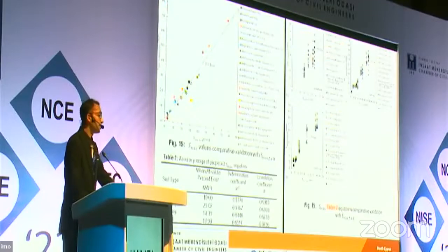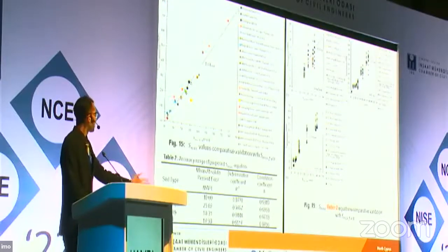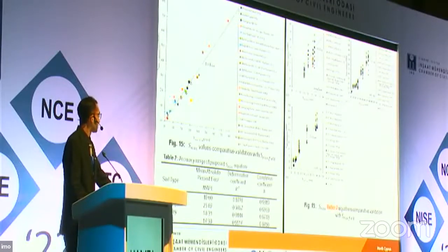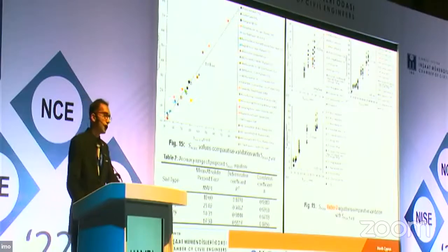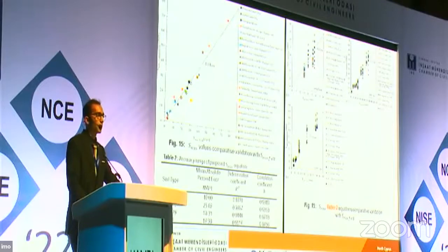So we have validated our modified equation with the field data, and overall the performance was quite good. Approximately 18% error was obtained, if you consider the many variations which are involved in the strata and other aspects. But in the beginning, I was mentioning that the inflection point equations can have a significant impact.